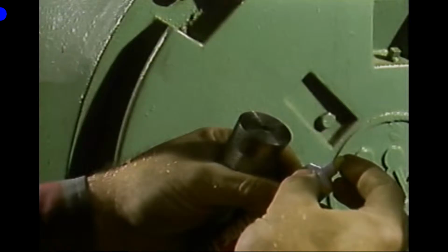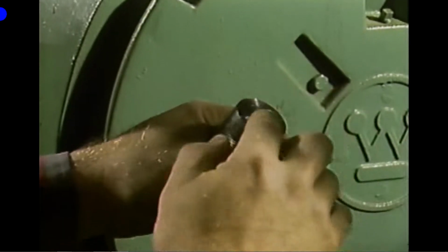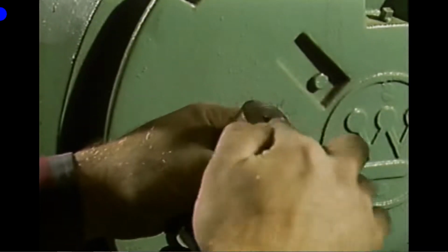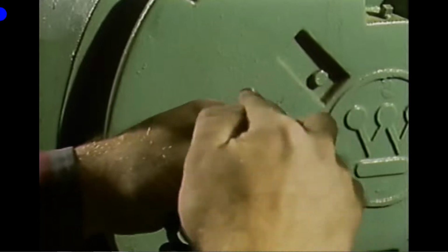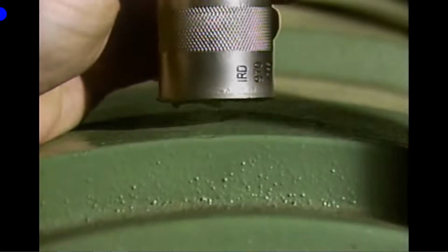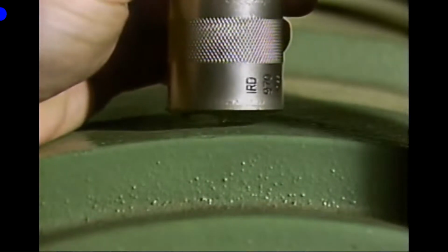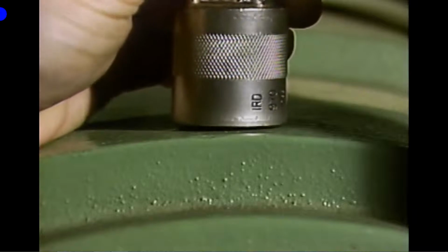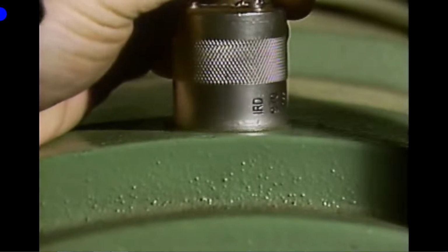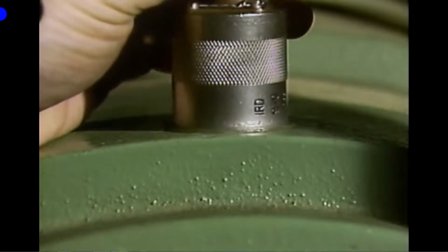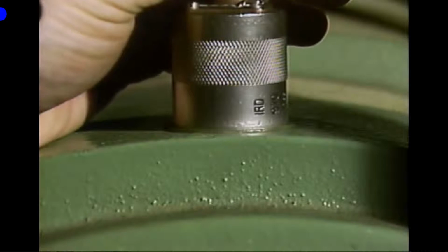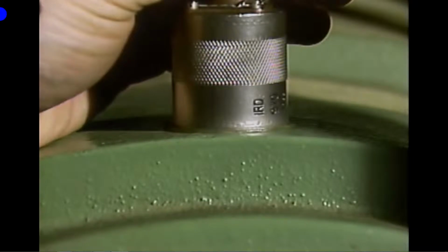Many transducer manufacturers recommend using a silicone grease between the transducer and the machine that's being checked. The grease helps fill any gaps between the transducer and the surface of the machine to ensure that there is a large area of contact. It also prevents the transducer from chattering on the surface of the machine.